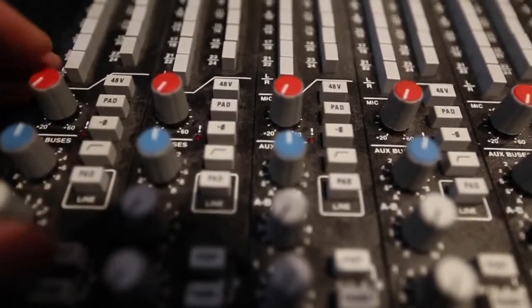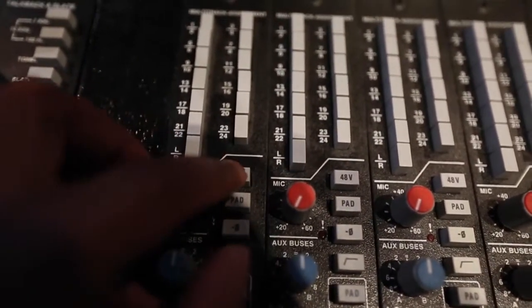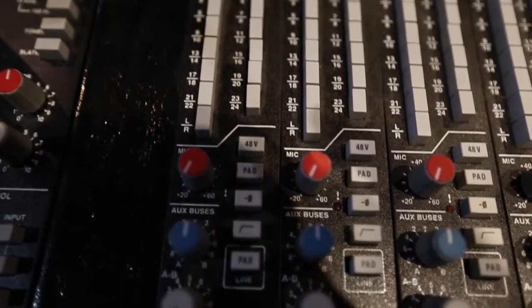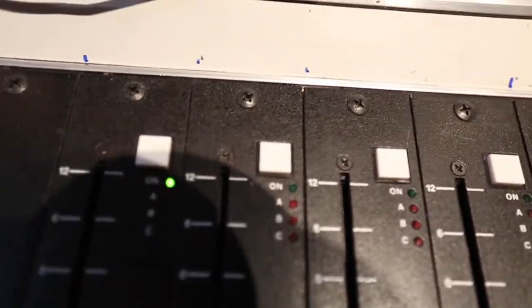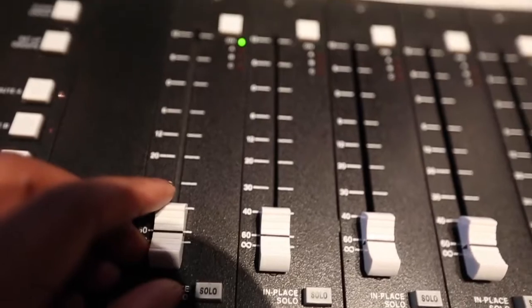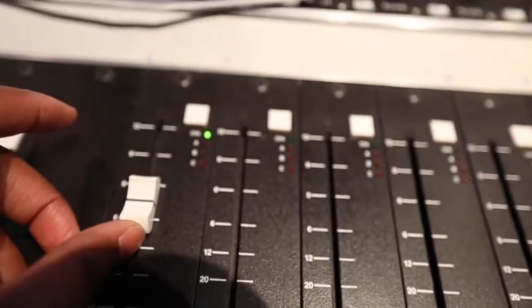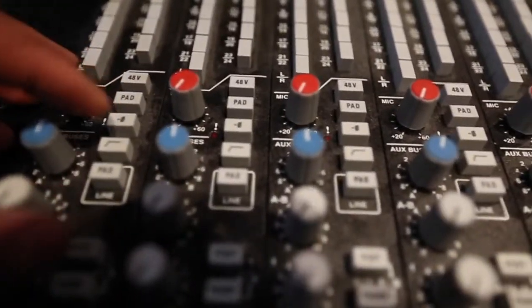While the desk is still muted, this is just to avoid any signal spike, we'll need to apply phantom power by pressing the button plus 48 volt. Condenser microphones require this small amount of voltage to run. The channel fader is raised to 0 dB and switched on by pressing the on button. This is to ensure the full signal is sent to Pro Tools.